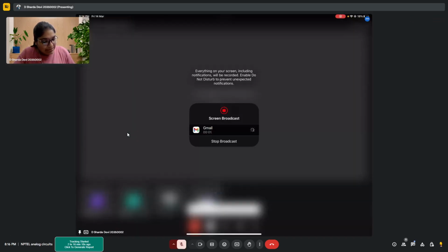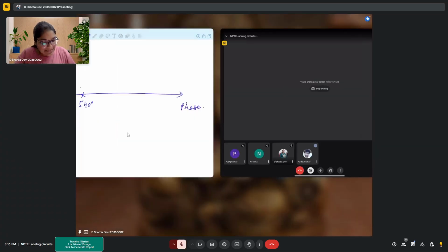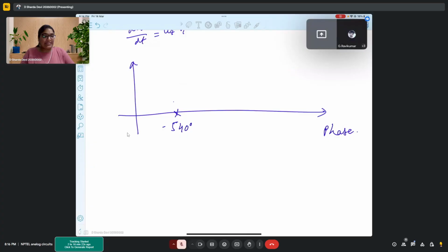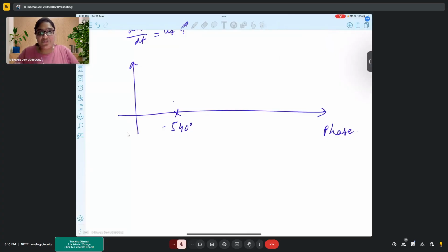So generally, what anybody has in mind is, if we are getting the phases in 0 and 360s factors, we will see an oscillation. That is correct. But the question is, are we observing the whole range of frequencies or not? Now, here what happened, for j omega equal to 0, the phase was given as 540. For j omega equal to infinity, the phase comes out to be minus 810. My question is how they got 540 and 810.